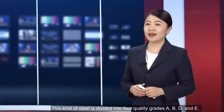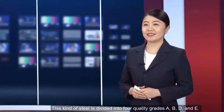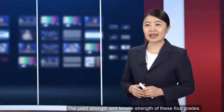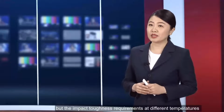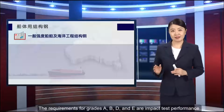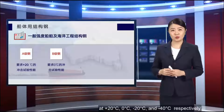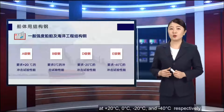This kind of steel is divided into 4 quality grades A, B, D, and E. The yield strength and tensile strength of these 4 grades of steel are the same, but the impact toughness requirements at different temperatures are different. The requirements for grades A, B, D, and E are impact test performance at plus 20 degrees Celsius, 0 degrees Celsius, minus 20 degrees Celsius, and minus 40 degrees Celsius, respectively.